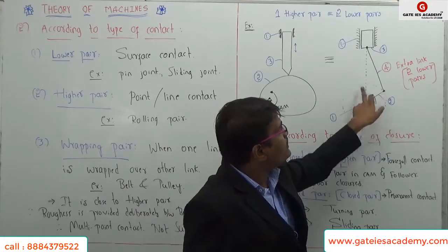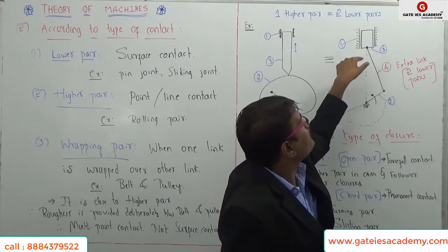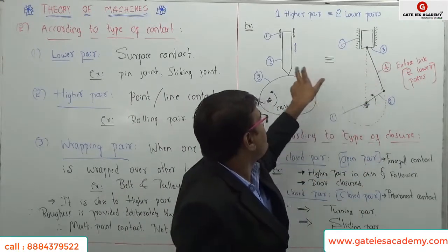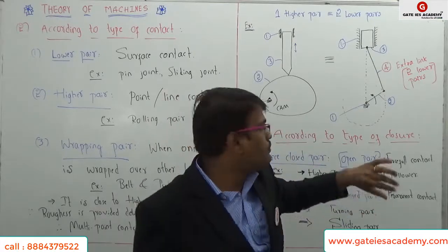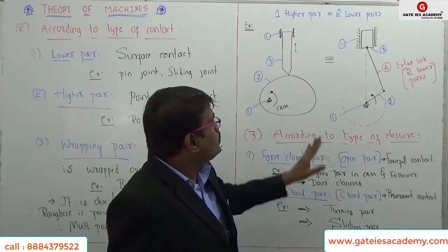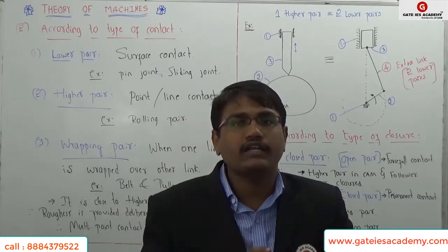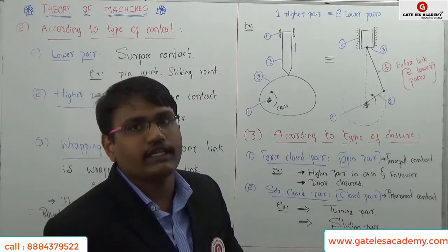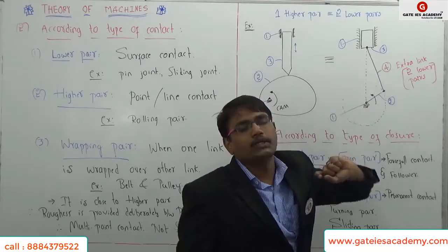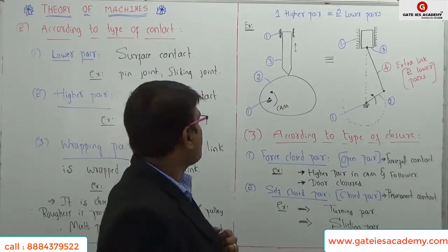See here, a crank is there, it is rotating, and there is a rod which is connected to this reciprocating part. So this will provide me the same kind of motion from rotation to translation motion, correct? So to obtain this one, there is a requirement of one extra link. One extra link means two lower pairs are there on that particular link. See here, one lower pair, another lower pair. So two lower pairs are needed extra to replace one higher pair.